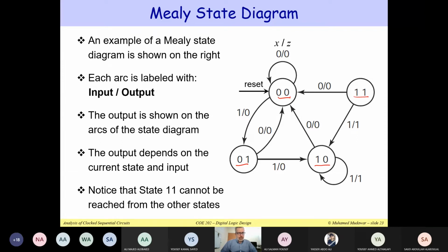Hammam, you had actually an answer for that? 2. Why 2? 4 states. Is it only because of 4 states, or is there another reason? You can see that we have 2 bits inside. We are storing 2 bits. So each state consists of 2 bits. We have 0,0, 0,1, 1,0, and 1,1.